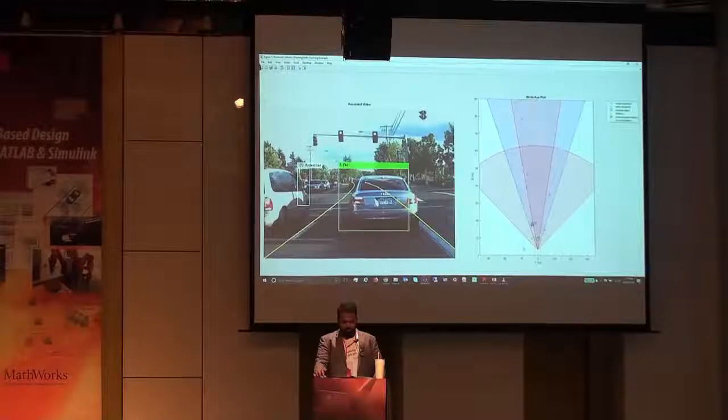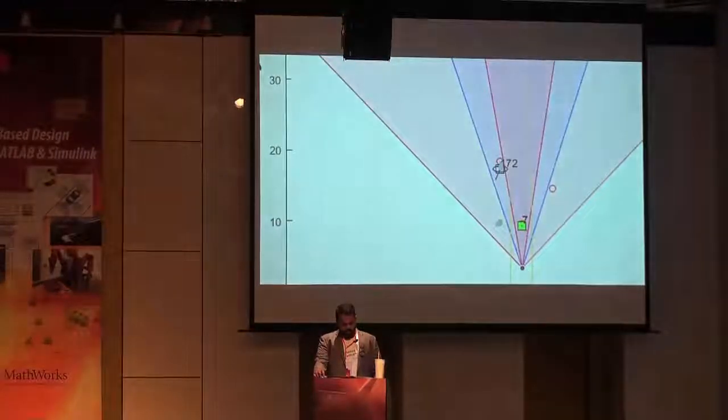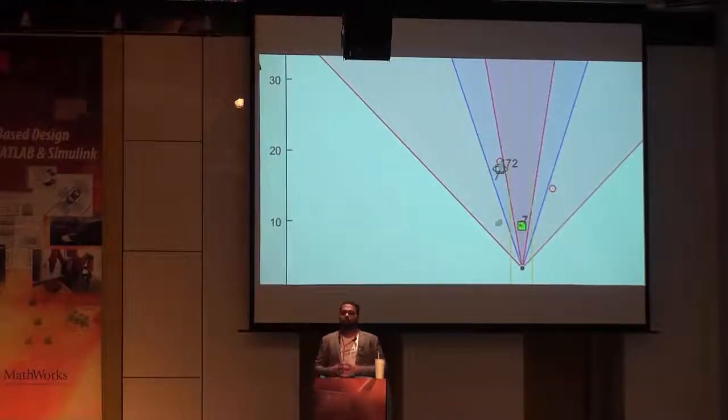So let me move forward with this, which is to say that here, the forward collision warning algorithm identifies the most important object by looking at the different objects that have been fused. Because of other sensors that we have, such as the IMU, which helps us determine our own ego vehicle's speed and direction, with that information you can tell if there's a possible collision. If you're going very slowly, it doesn't matter if there's a car close to you.